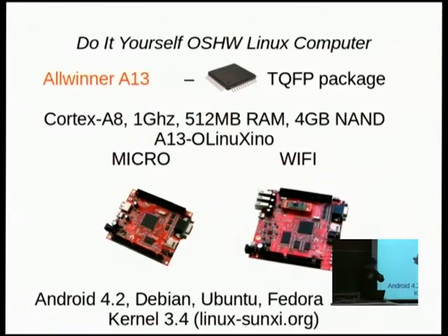Of course, it had its price here because the RAM for this processor is not available in TQFP package. But still, this RAM chip is with only 30 solder balls. So, not so difficult. If you are skilled, you could eventually reproduce it at home. And of course, it's a trade-off. You cannot have the fastest processor, the fastest technology, and have it built at home. So it was a compromise, but still a computer which you can build at home.